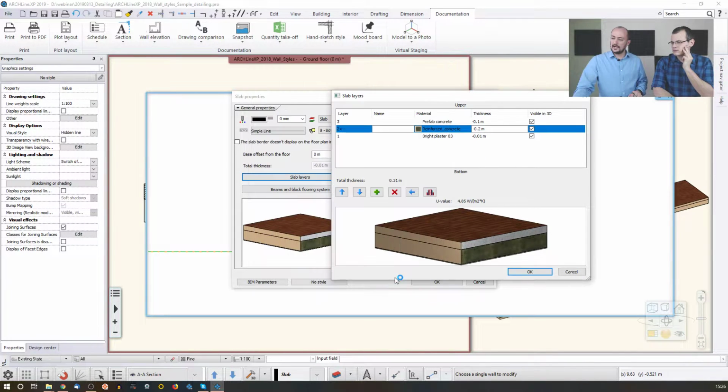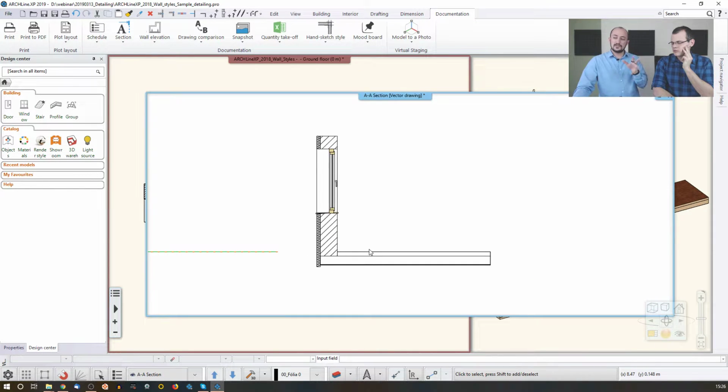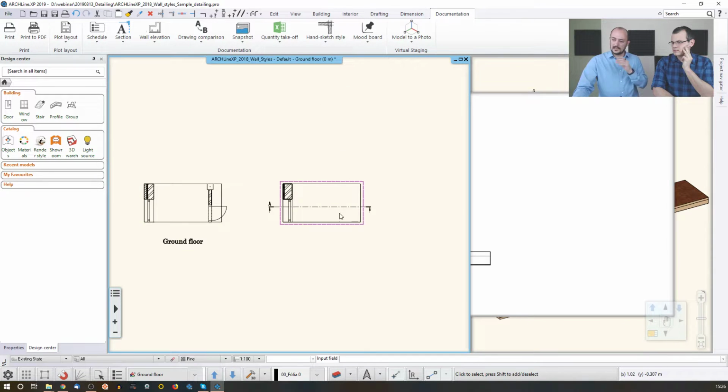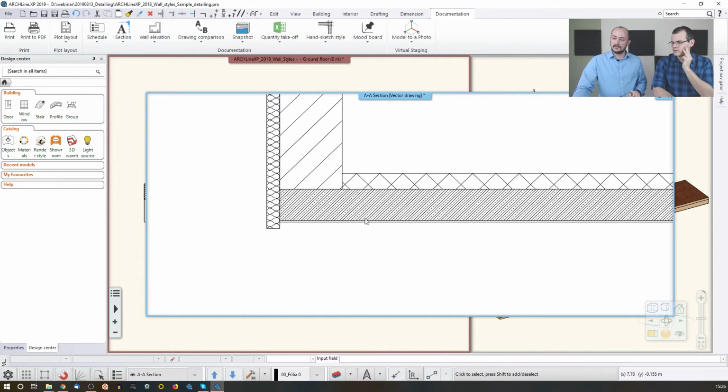So when I do that, and I just close these things up, and if I use this material all around, it won't only be updated here when I choose to update this section, but it will also be updated everywhere else. Yes, that's a quick good disclaimer that this is not only a localized change, but also a global one, because now we are changing a material setting which is in our object library. So this is going to be changed everywhere where this thing is present.